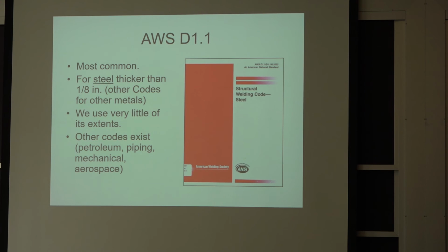Making a commercial building, for example, well, it's pretty clear because the building code just says, if you have structural components, they need to conform to AWS or the Steel Welding Institute. So it's for those other situations, and with aluminum, a lot of times it's the Aluminum Construction Manual from the Aluminum Association that's used a lot. But again, you have to say, this is what you want. This is the electrode I'm looking for, and this is the kind of quality that I'm looking for. This code by default is only going to require a visual inspection.